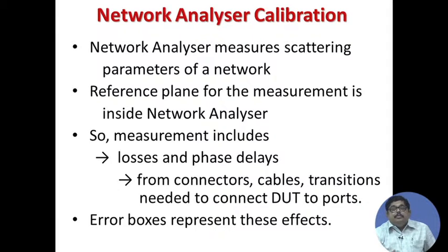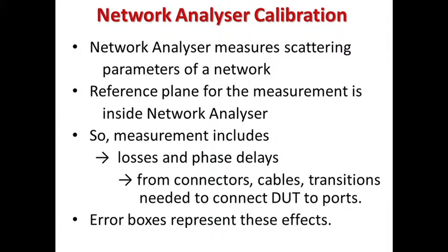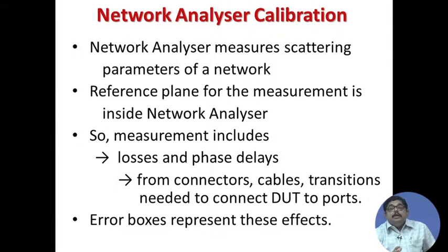Now, when we discussed the architecture of the network analyzer, we saw that the measurement of scattering parameters is reference plane dependent. If you change the reference plane, the S parameter measured by the network analyzer gets changed. Now, in the network analyzer, its reference plane is quite inside the instrument.